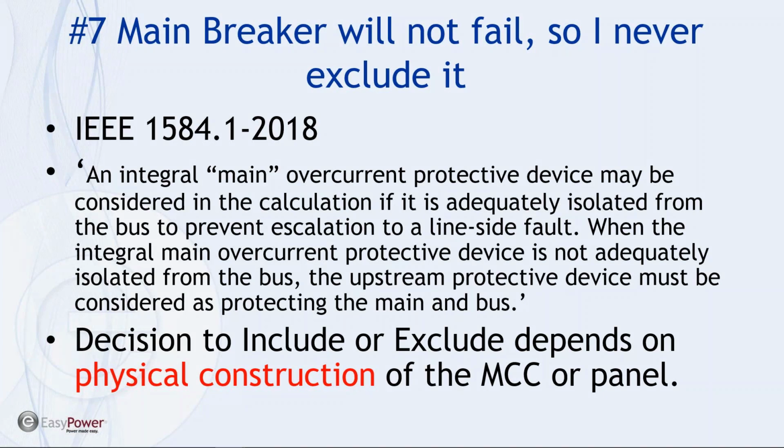Number 6, the main breaker will not fail, so I never exclude it. We saw this in that previous one-line diagram that I looked at. He had a setting where all of his main breakers were included in the calculations. IEEE 1584, the latest version, and this verbiage was in the older standard,